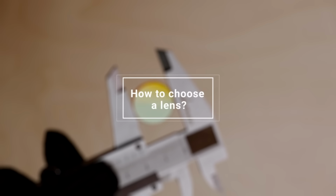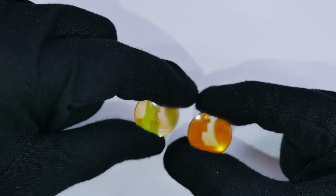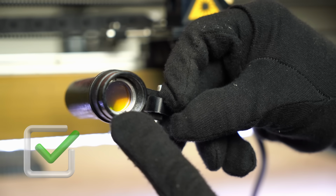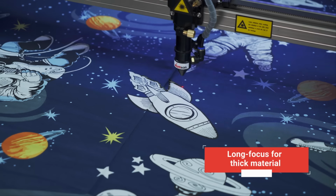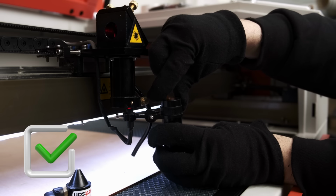How to choose a lens? Your checklist for this task. Verify the material. Zinc selenide is preferred. Look at the production method. CVD lenses are long-living, work with high powers, and have better focusing results than PVD ones. Diameter should match the diameter of the cone. Focus: short focus for engraving, long focus for cutting, and medium focus is universal. Form doesn't really play that big of a role for CO2 laser machines. It's important to install them with the convex side facing the laser.